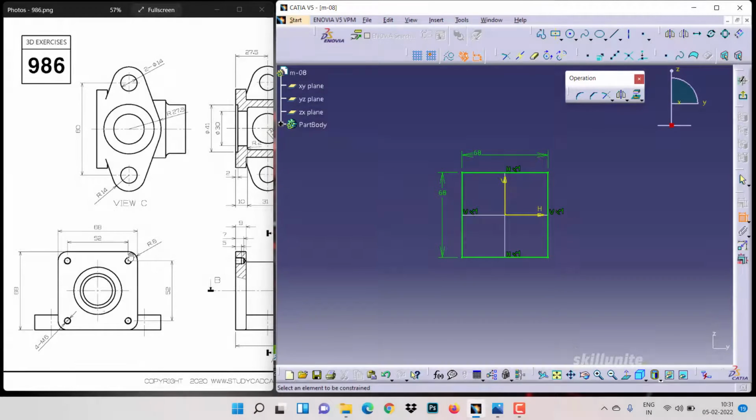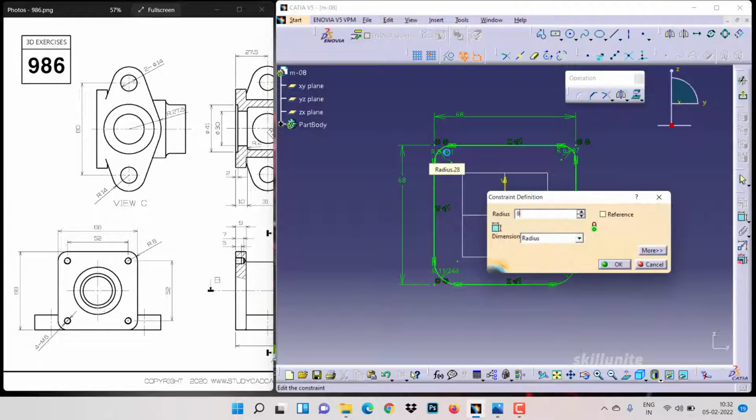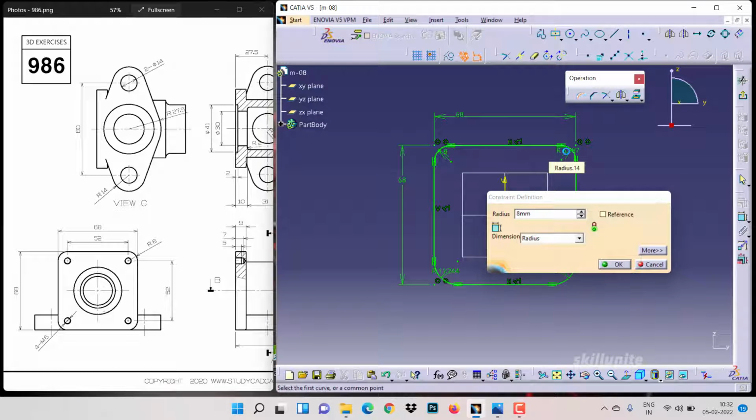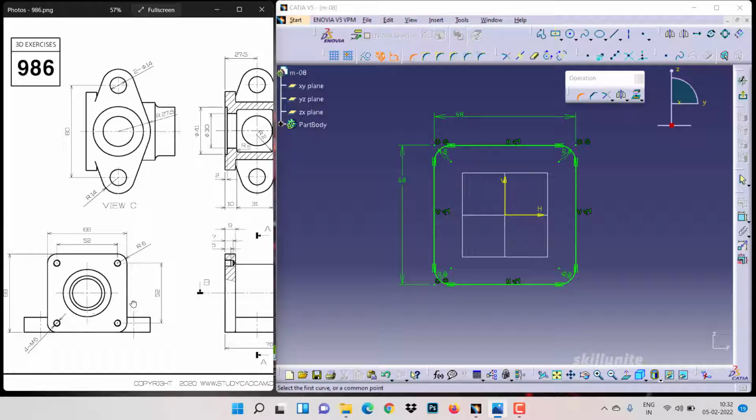As you can notice, it is containing a fillet of R8. So we will create fillets as well now. So mention the dimension as 8 mm for the fillets. Then this cutout, whatever you are seeing over here, we will do it later, but we will create this hole. As you can notice, the diameter of it is M6. That means that we cannot do it here in sketch. So we will create it once the solid is done.